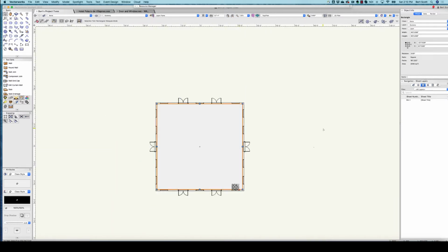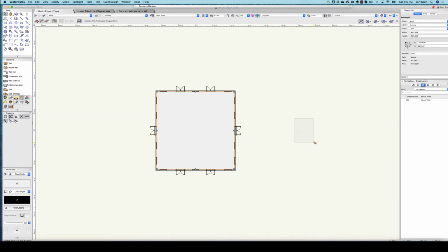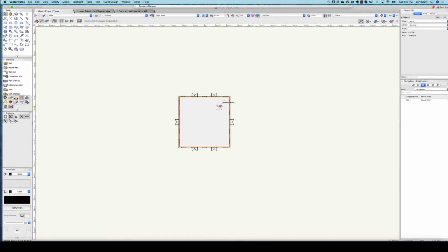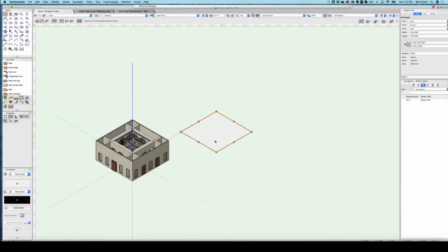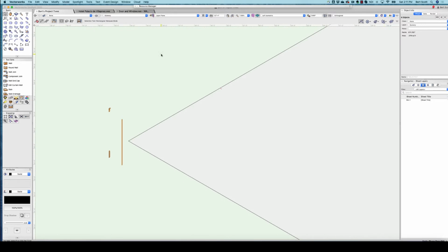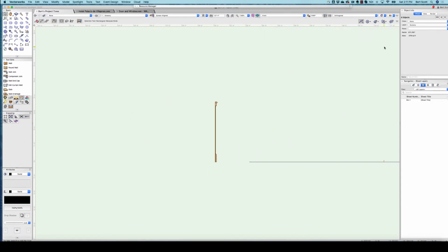And we're going to use that rectangle. It's actually going to be easier if I move it out of the way and put it over here. I'm going to go to isometric. So these are in different planes. They should be in the same plane, and the easiest way to deal with that is I'm going to go to front, and put them in screen plane, sorry. And then put them both in working plane.